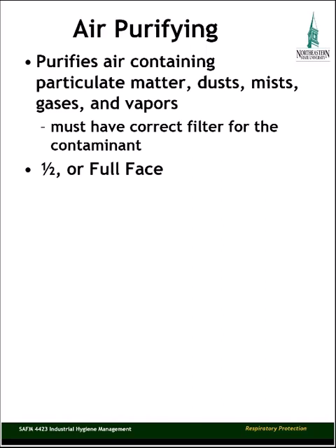You used to see quarter face respirators that basically just covered the mouth and the nose, but those are not common any longer. I don't even know if anybody sells those anymore. If someone's wearing a quarter face respirator, it's probably an old one that they had in the closet somewhere, and if it's that old, it may not be suitable for use. Most of the air purifying respirators are going to be the half face respirators.